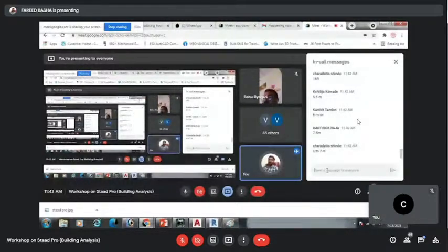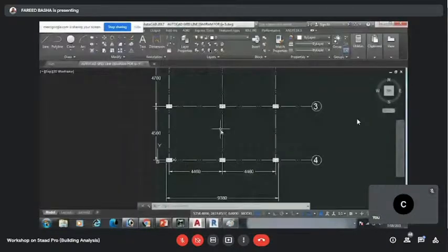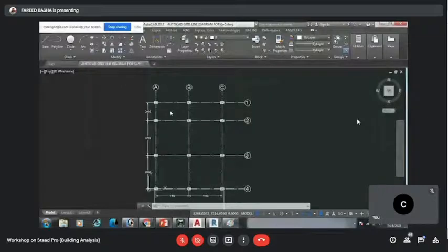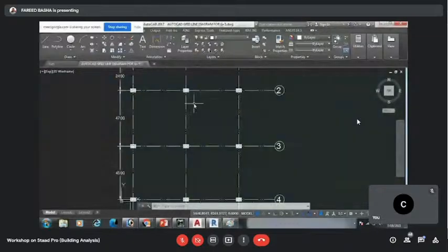You can go from 5 meters to 8 meters also, but the structure has to be very large, so the risk will also be a little higher for us. So 5 meters is the safest distance. So I have taken 4.4 meters here, right? So you can see, in total I got 12 columns. This is my veranda and this is also my slab, and here I am not taking any slab because I am getting staircases here, right?